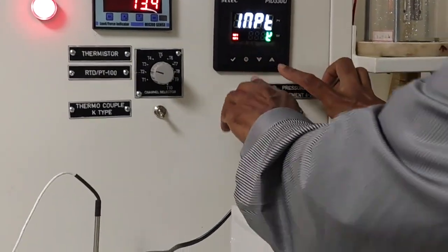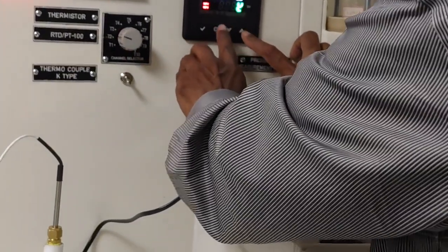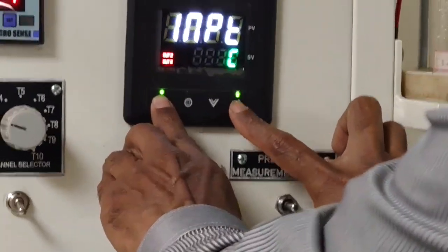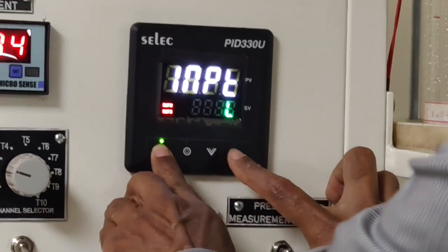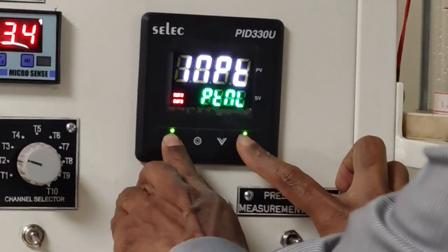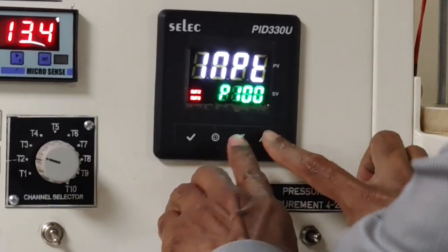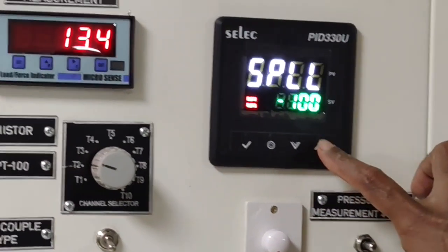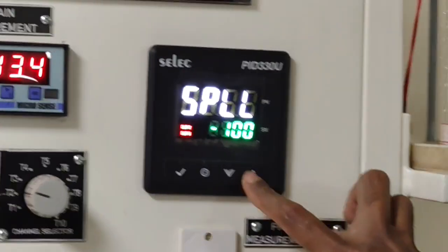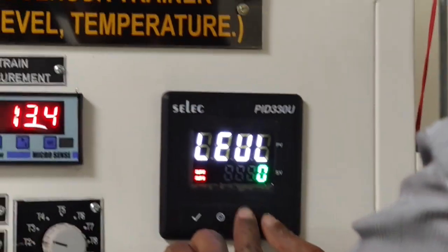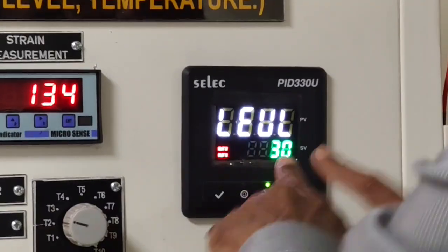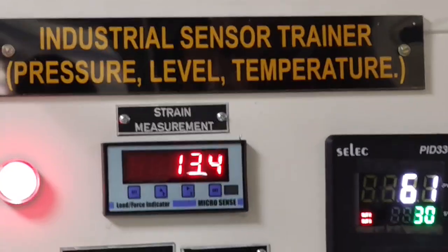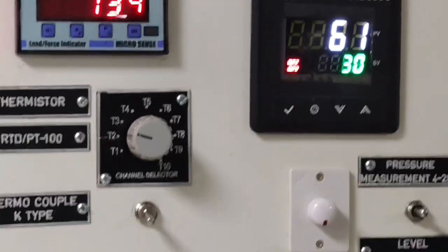This you have to change to PT 100. K is only showing, K is there, no? Then you have to input. You have to change it to PT 100 now. This is PT 100. Now resolution 1 degree centigrade, 850 high scale. Those scaling is 100 minus 0. Now it will read. Okay. That time it was not reading. It was reading only room temperature because we have not done the scaling.